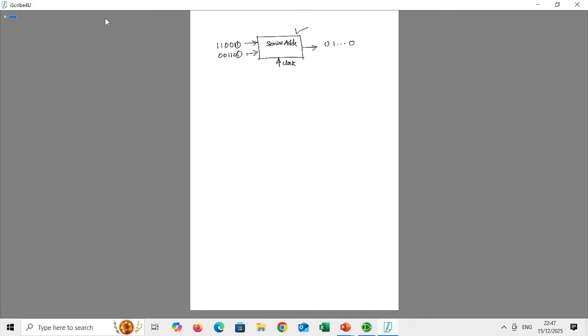Let's take another example. We are building a digital system, again based on the clock, and we have to identify, in a stream of serial input derived from another digital machine or industrial output, a 110 pattern. The sequence will be binary data. Whenever the 110 pattern is identified in the binary sequence, I have to generate an output signal indicating that the pattern is identified.